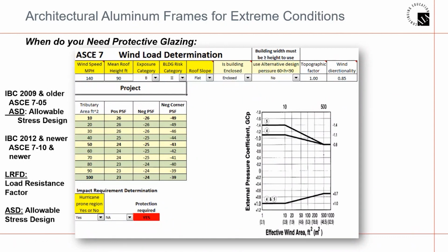There are 3 variables that go into determining the wind load on each project. The wind speed in terms of miles per hour from the appropriate IBC map. The project exposure is called out. Then the project importance factor must be indicated. This information is typically provided in the general notes page of the structural drawings.